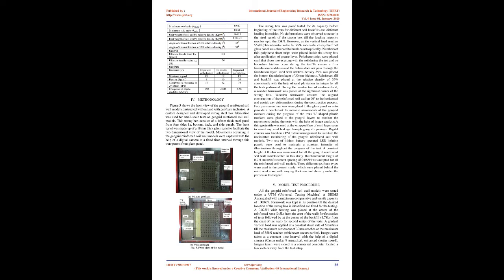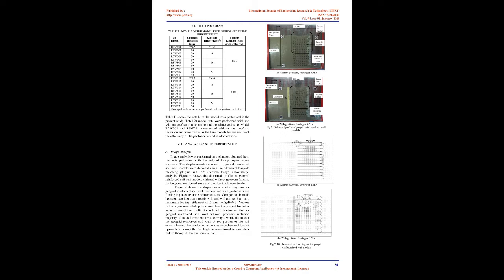A. Model sand. B. Model geogrid. C. Model geofoam. Fig 2. Photographic view of model materials used in the present study. B. Geogrid. The geogrid was selected on the basis of its physical properties and its resemblance to commercially available geogrids. The model geogrid falls in the category of high-strength geogrids. The pattern, opening area and rib dimensions were chosen such that they resemble the prototype geogrids available in the industry. To ensure identical frictional bond behavior, the percentage opening area was chosen to be within the bandwidth of up to 90% of that of the prototype geogrids.